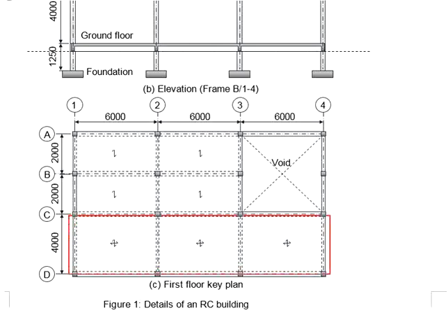As for this slab here, the Ly per Lx ratio is less than 2.0. That means you know that the loads is going to be two-way. And there are two methods for you to calculate the loads. First is by using the yield line method. Second, it will be by referring to the table in British Standard 8110.